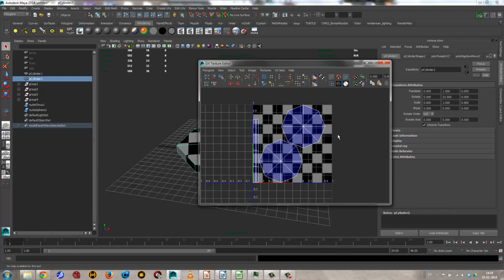You can relax the tension between points here compared to the space in world space, so that will make the relative shapes or sizes here correspond better to the world space, which is actually what you want. And you can also do an unfold, which is this tool called smooth, funny enough, but this is actually unfold and smooth. So this is one of the big